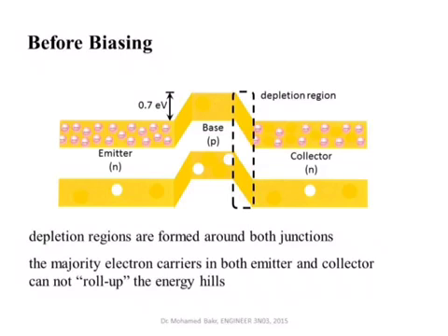From our previous studies of PN junctions, we know that when you put a P-type material and an N-type material together, this creates a depletion region on contact. In a few microseconds maybe, this will create a depletion region, and then you end up with this sort of barrier. So this is a P-type material, this is an N-type material. You can see the electrons in the conduction band of the N-type material. Their energy is not sufficient for them to cross into the conduction band of the P-type material. So this is why, in steady state, they cannot cross from here to here and create a current. So this is the emitter, this is the base.